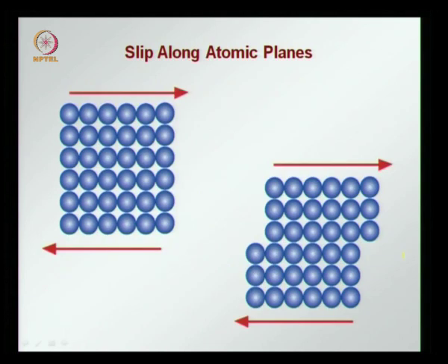So you have here a structure with closely packed atoms. All these planes here are the packed planes, and if you apply a shear force, what you will see is that the slip does not cut across the closely packed planes but goes along them, like what we see here. So here you see how slip occurs: along the closely packed structure and not against it or across it. This happens because it requires the least energy for creating the slip.